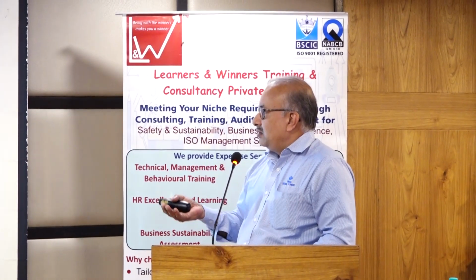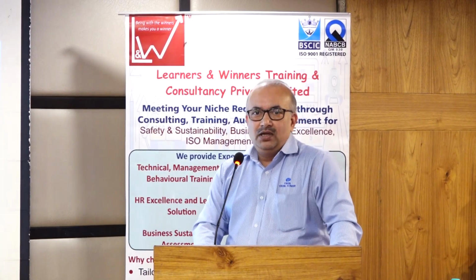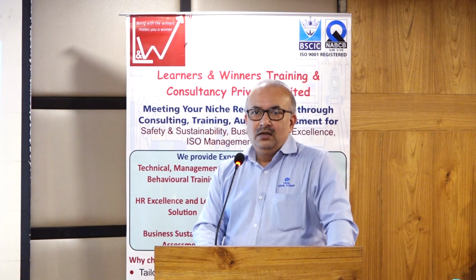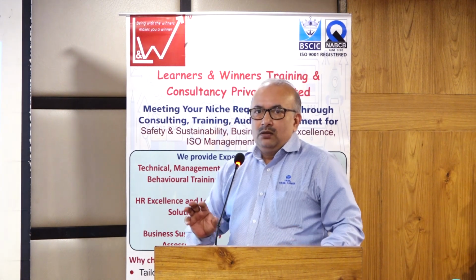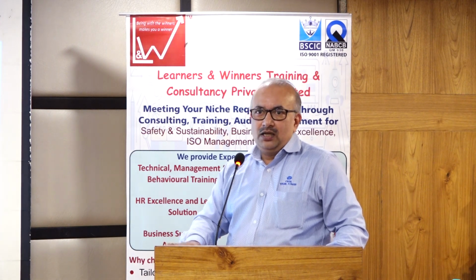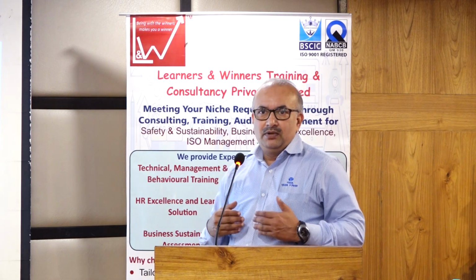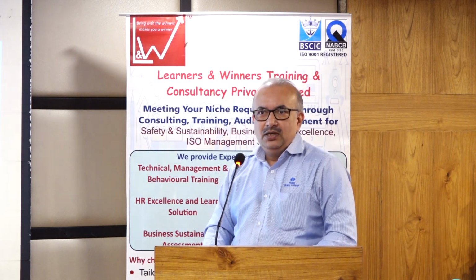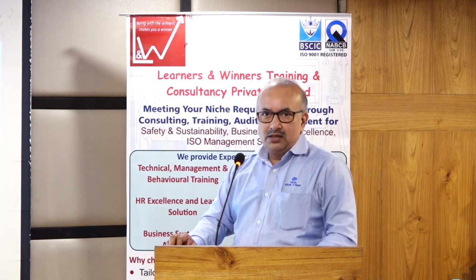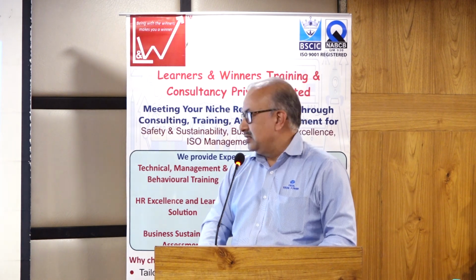The system of the compressed air: a coal-fired thermal power plant normally has three types of compressed air. One is for the instrument, another is for the ash plant requirement to convey the fly ash from the ESP collected hoppers, and the service air that is used for cleaning and other purposes.